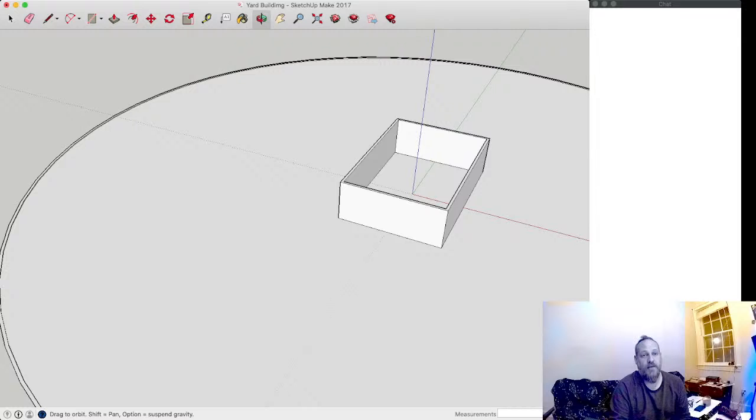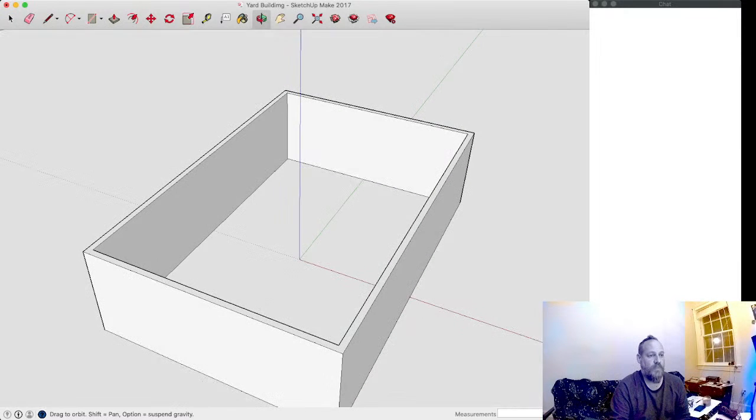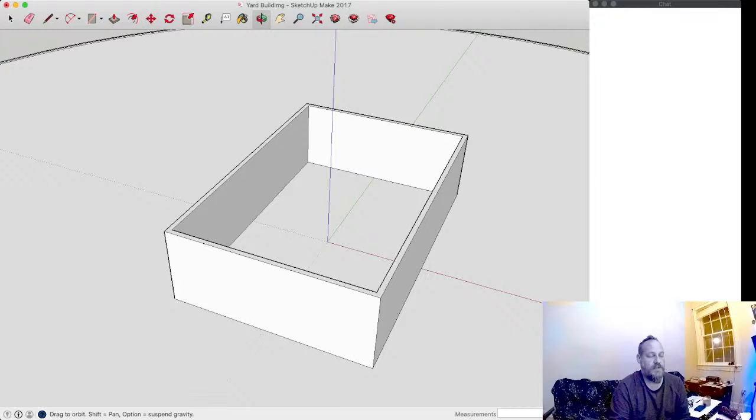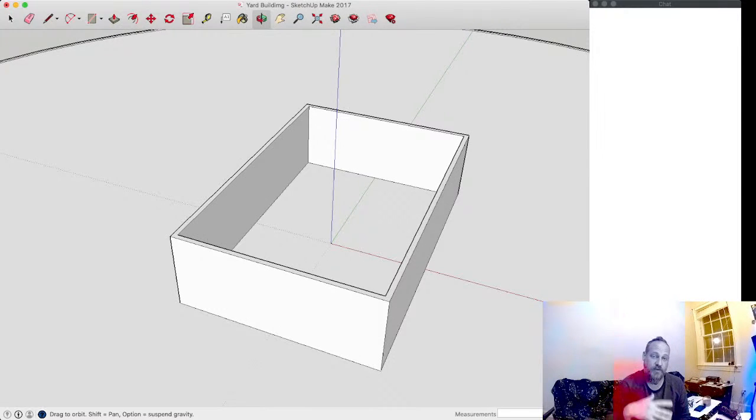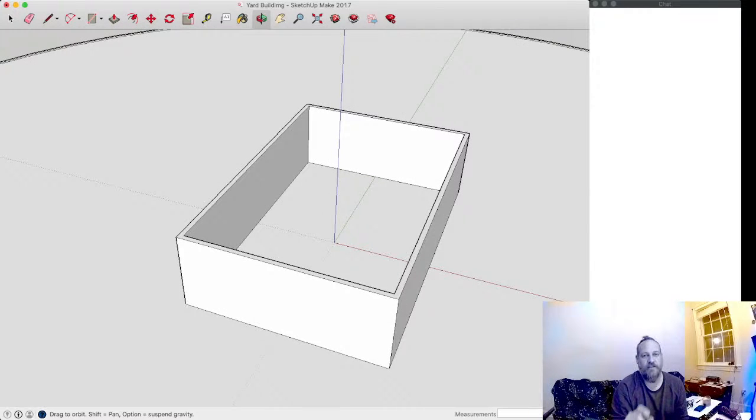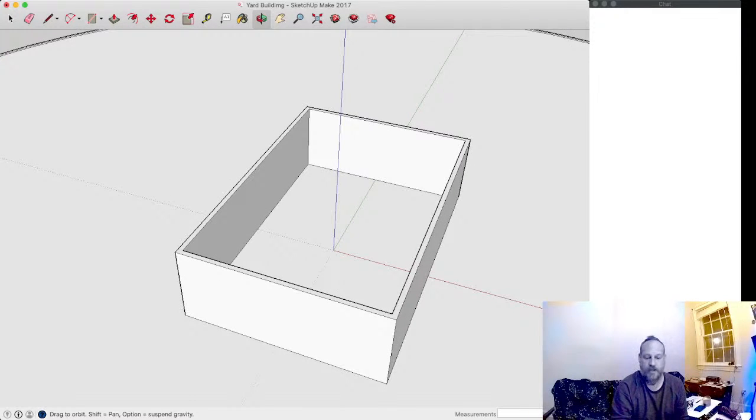Now, you can build below ground in Spatial. So if you build any piece of architecture that has a basement or below level spaces, you could build under this. You'd probably want a thickness to a floor, because if you point your controller into what was gray in SketchUp, your controller will go through it. So you could go back through the roof of something, which maybe could be fun in some ways. You could hide something that way. I would say give a thickness to every wall and floor that you create.